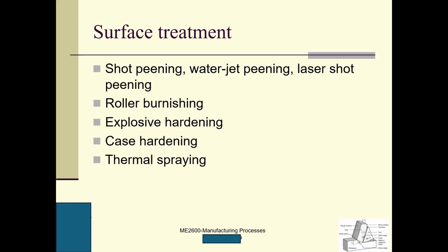After some time, the carbon atoms will come to the surface of my workpiece. As a result, the hardness will be enhanced and compressive residual stress will be induced. Fatigue life will be better. Okay? So is your answer the same as mine? Great. As I said, I'm going to test your understanding of case hardening in our exam.